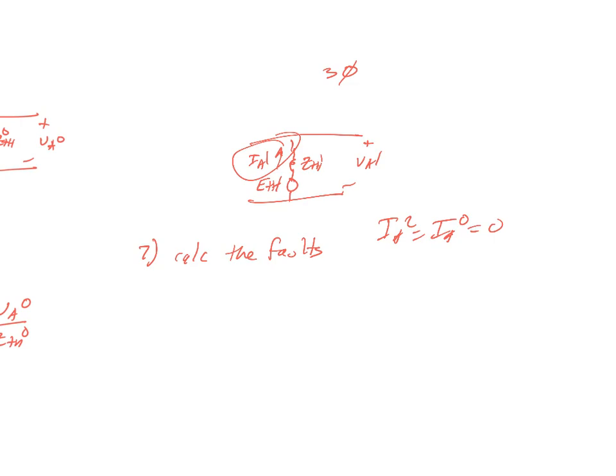You can also check if you want to do it for the three-phase fault, but you're going to have 11 buses where you have to look at these Thevenin equivalent impedances and voltages. You can assume one at an angle of 0 for your Thevenin equivalent voltages. Assume that the system is initially unloaded, and you can get some pretty darn good results that way. And then your last step for this lab is find the max fault current.